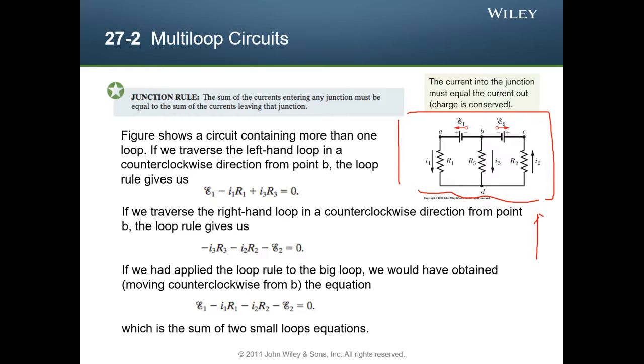So these two circuits are equivalent with each other. The condition is that V equals IR. The R should be the same, and E and R should satisfy this condition. Then these two circuits are called equivalent circuits. Equivalent means if you put it in a black box, you can test the voltage and current relationship.